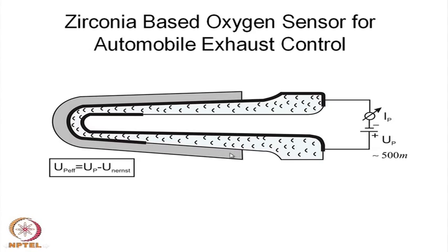And then this is a kind of porous shroud which protects this particular thimble, and this black area is actually the electrodes. So, the outer electrode comes up to this end, and the inner electrode also comes through the inside wall up to this end. So, you can measure the EMF from these two points. Not the whole of it acts as the electrode; the active electrode area, the active cell area, is basically this much, and the painted portion basically acts as a lead and connection for the electrodes. So, this is a very simple system, but it has tremendous use.